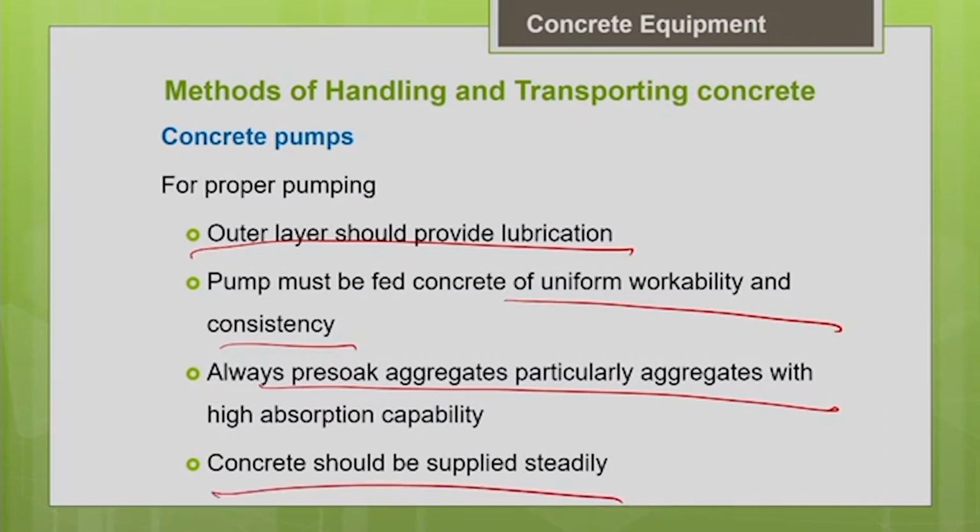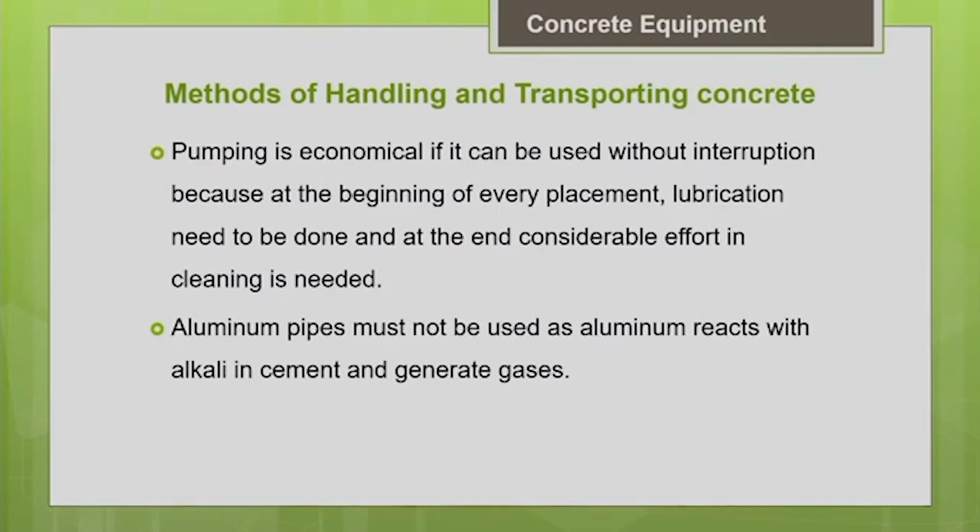As I told you, it involves a lot of preparation procedures, like you need to do the lubrication. After pumping you have to do the cleaning. All this involves a lot of effort. So for a steady supply of concrete this is the best choice, but for intermittent placing of concrete, pumping is not the right choice. So pumping is economical if it can be used without interruption.